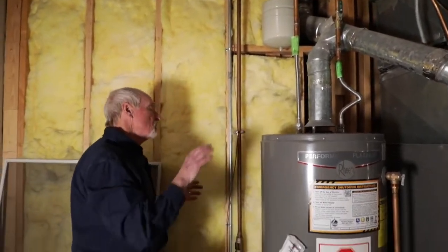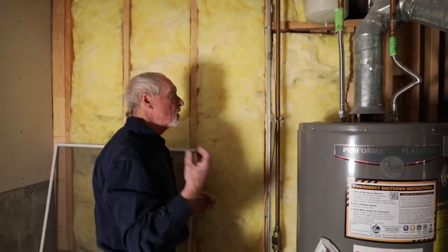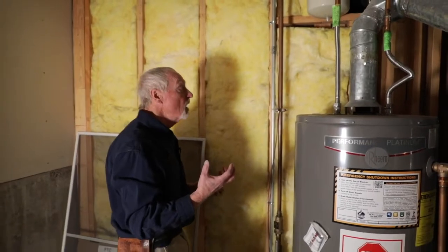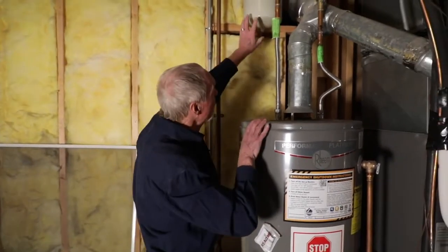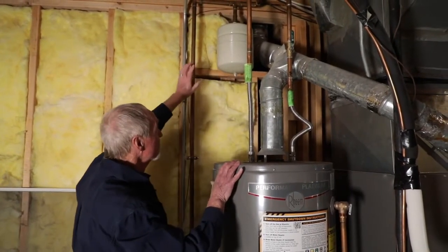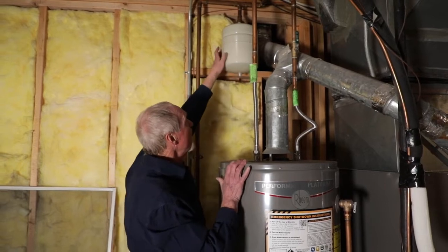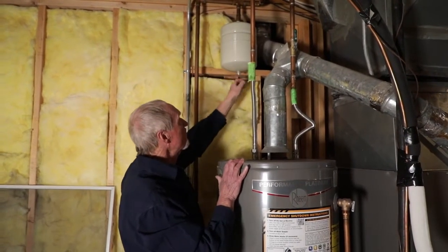The reason for this is when the water heater is heating water, it can dramatically increase the water pressure in the house, and by a lot in some cases. And so we want to absorb that excess pressure by some way, and in this case using an expansion tank, which has a rubber diaphragm in it. We have air in the bottom of it, and then we'll have water in the top of it.